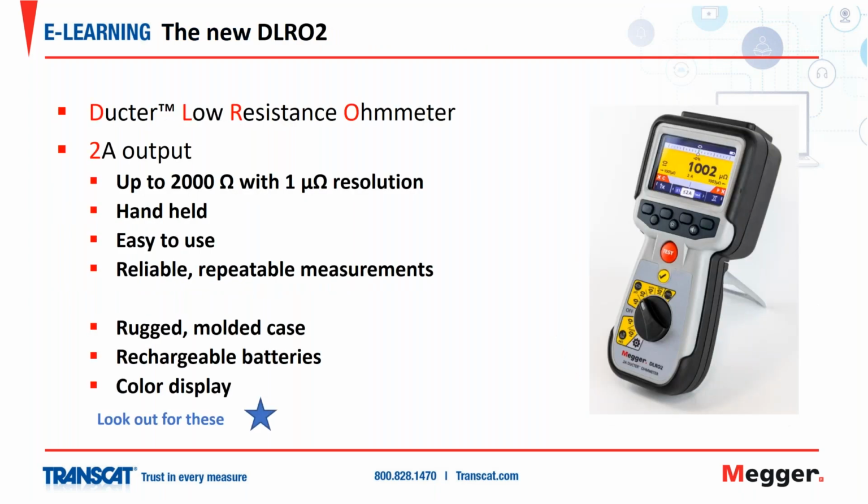So now we'll get into just looking at the DLRO2, at this model. Again, the Ductor low resistance ohmmeter. It's got 2 amp output. Can read up to 2,000 ohms with 1 micro ohm resolution. It's handheld, of course, easy to use. And maybe most important here is it provides reliable, repeatable measurements.